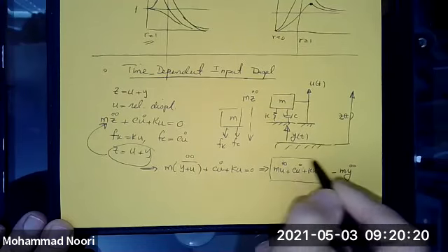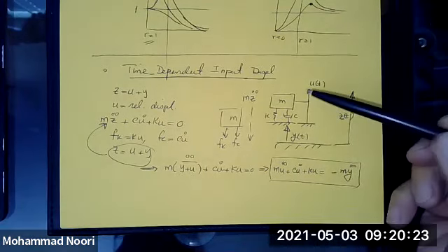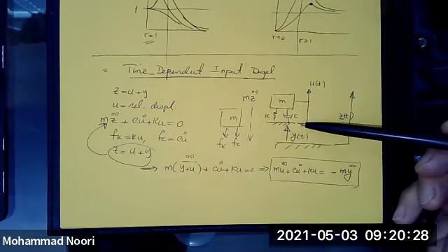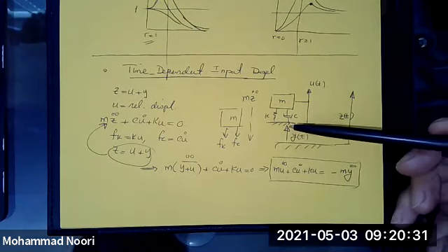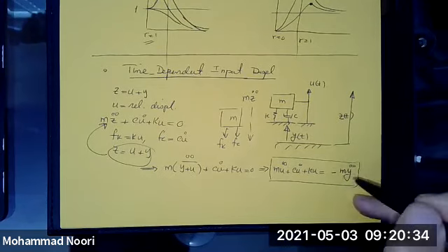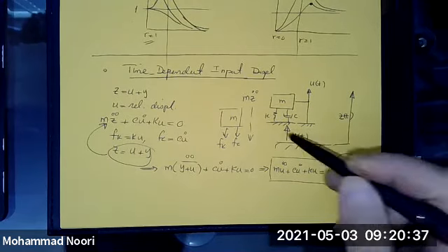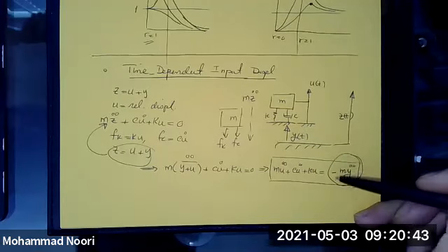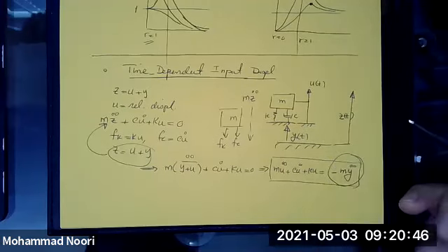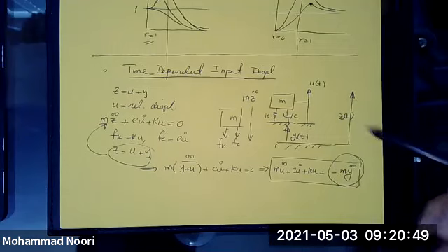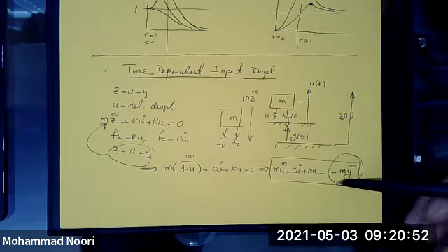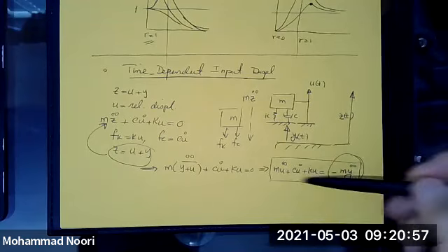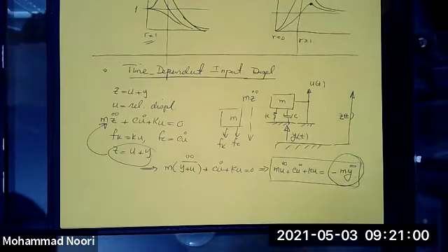This is the relative displacement of the structure with respect to its base, where that is subjected to an input displacement. The right-hand side, which is the forcing function, would be the mass times the input acceleration. This is the form that is of interest in structural engineering, structural dynamics or earthquake engineering, when you have, for instance, earthquake records that are given in terms of acceleration data. So that's how you can find the displacement of the structure.